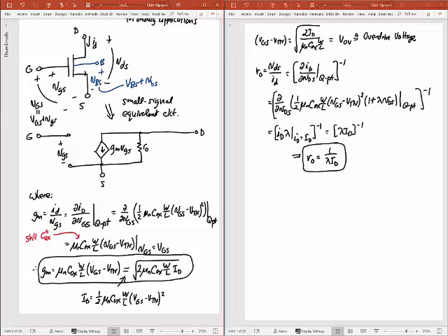So I'm going to go ahead and do that. I'm going to add one more voltage controlled current source here, just like the one over here, except this one now is controlled by the body effect. And so I'm going to call that GMB, and that's going to be controlled by this small signal voltage, little VBS. Okay, this is an often neglected thing. But for short channel devices, this becomes more important to include in the model. Okay, so in modern times, we're seeing this modeled more often.